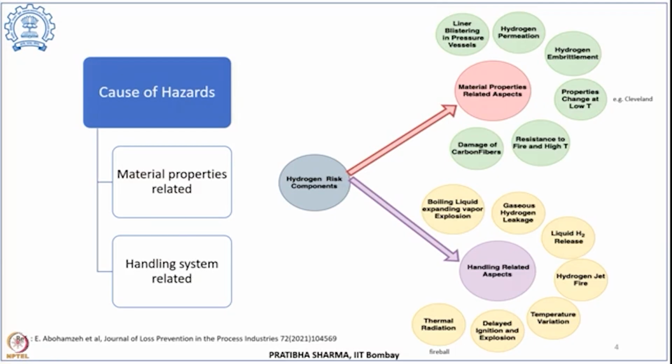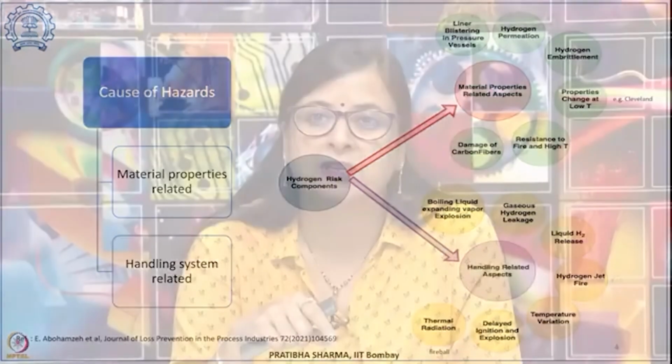Now, hydrogen embrittlement is a complex phenomenon and it depends upon several parameters. It depends upon the exposure time, the purity of the metal, the concentration of the gas, the temperature and pressure conditions, the surface properties and mechanical properties of the material, what alloy we have selected, and the grain structure and microstructure of that material. So, it depends upon several characteristics.